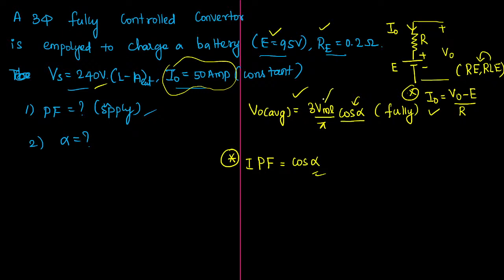According to the given data, we can calculate the maximum line voltage. First of all, listen: the RMS voltage per phase is given, line to neutral only. I told you this is line to neutral, meaning per phase voltage, given as RMS. So it is 240 volts RMS, but I want the maximum voltage first.